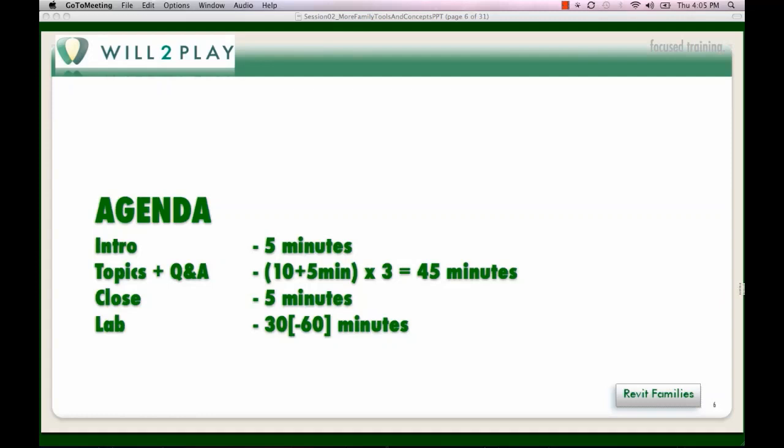Yes, what Daniel said. Standard families are the loaded families for 2010. That's correct. The families that you can load, like the table we made last week on Monday, would be considered a standard family. System family is things like walls and floors that are project specific. No, let's just say that they're managed by Revit.